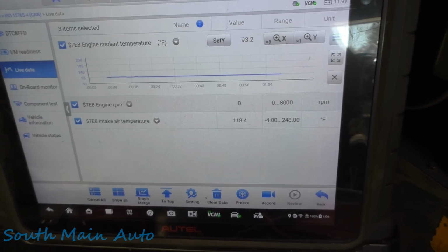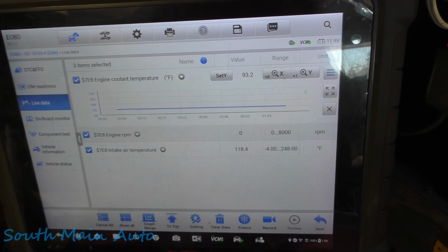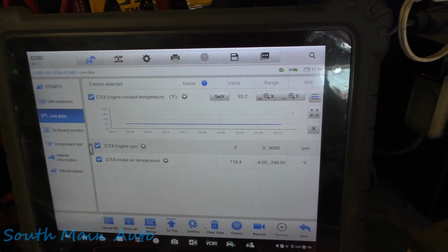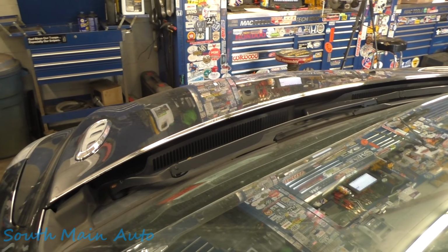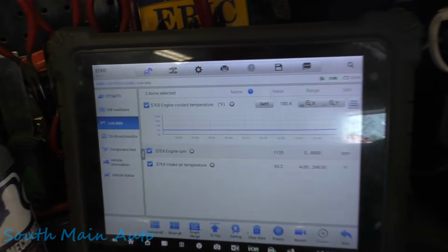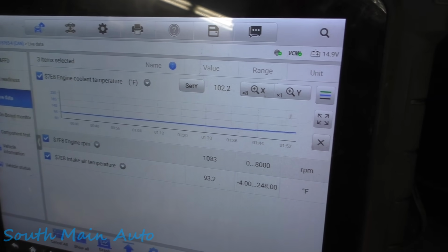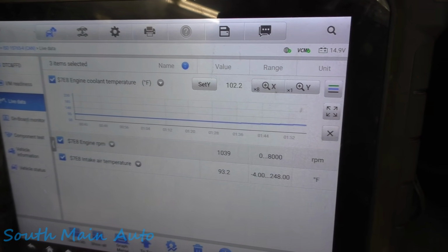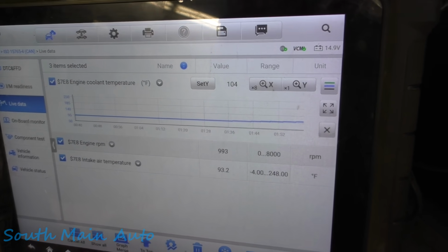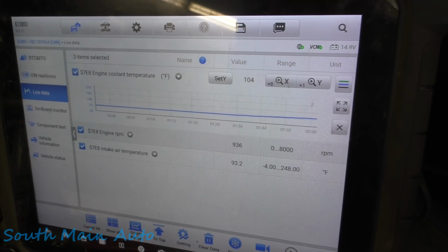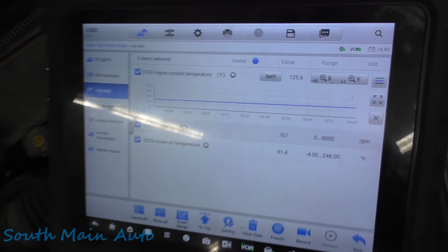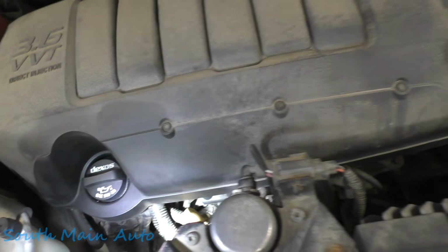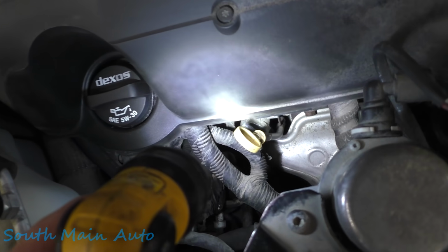So I'm going to take and start it up, and then we're just going to see if the coolant temp sensor glitches just during normal startup, and then we'll do a visual inspection, maybe wiggle the connector, things like that. If that makes sense. So I'm going to watch this warm up. If it does something funny, I'll kick the camera back on, but in the meantime I'm going to look up where this coolant sensor lives. But I just kind of want to let it go on its own for right now before we touch anything.